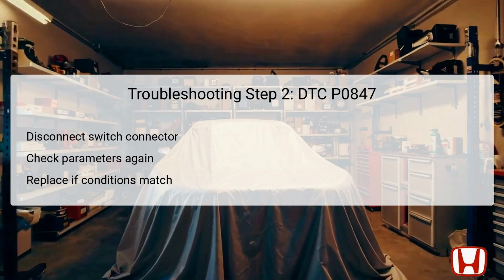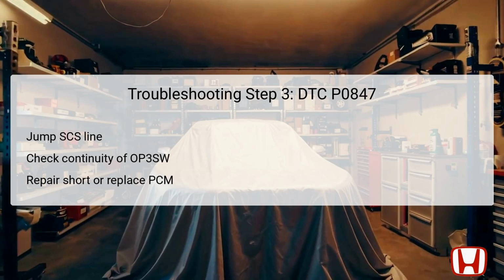Focus on the condition of the third pressure switch and verify if it reads off. If the conditions correspond to expected thresholds, then this implies that the switch itself may be defective and will require replacement. On the other hand, if the readings are not matching, it suggests looking into further diagnostic steps to isolate the issue.